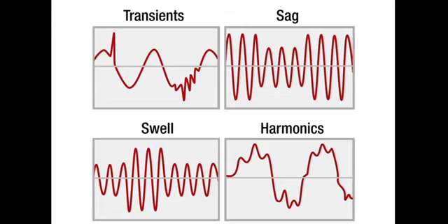Voltage unbalance. Unequal voltages in a three-phase system can lead to uneven load sharing and reduced efficiency in motors. Power factor issues. A low power factor results from reactive power consumption in a system. It can lead to increased energy costs and reduced system capacity.